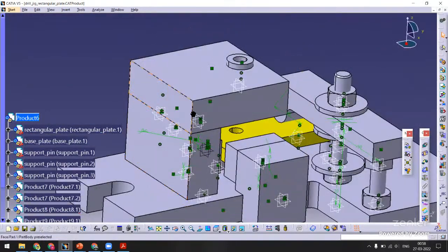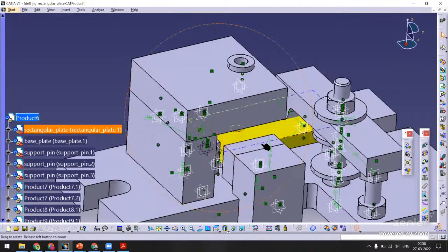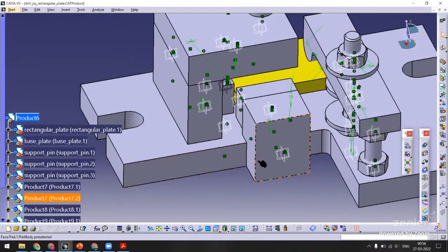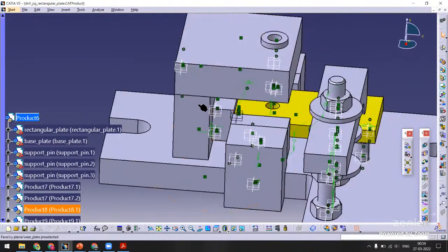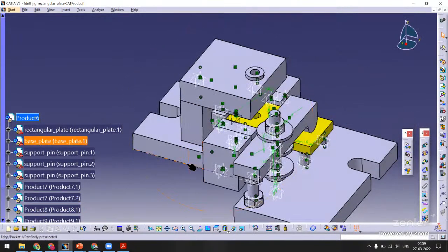Right now, they're all sitting, like for example, this block is sitting on this plate. This is possible only in the CAD. In reality, if I place it, this is going to fall down. So I have to make some holes and apply some fasteners to complete the design. The same applies with this block, this plate. I can't just place them. They are sitting because I have designed it in CAD system. In reality, if I'm going to put this block and then put the wear plate like this, they're all going to fall down. So I will have to apply some fasteners, even in the 3D design.